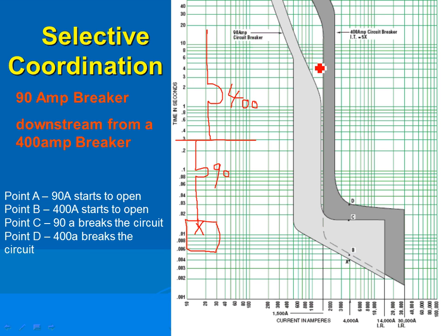Right in here, can you see that area? This is where all hell breaks loose. Meaning if you have a short circuit in this high area, it looks like it starts at, say, 1500. Sorry, 1000, 1500. It starts right here at 1500. At 1500, if the short circuit is 1500 or higher, it's a race between which circuit breaker is going to trip.